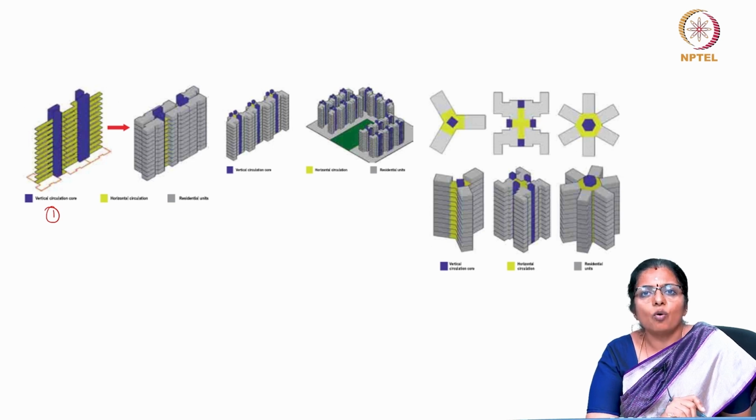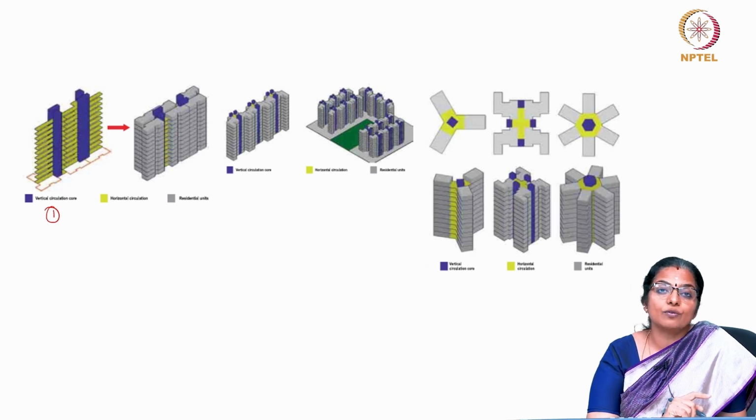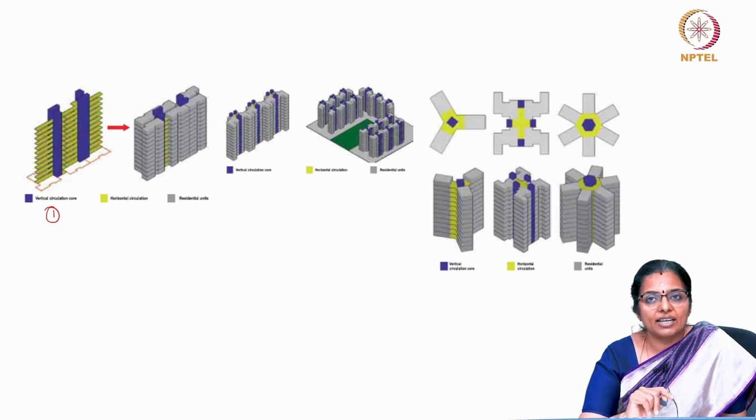A very old, traditional solution, particularly for flat land, is a compact inward looking building with an interior courtyard. And we will see more of this when we look at a case study of Jaisalmer much later in the class. This minimizes the solar radiation impact on the outside walls and provides a cool area within the building.